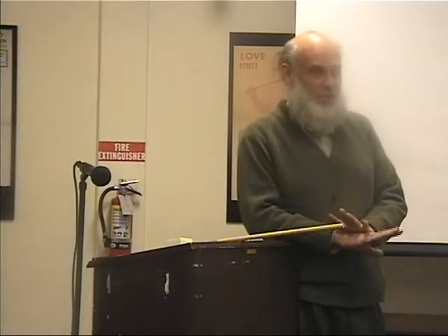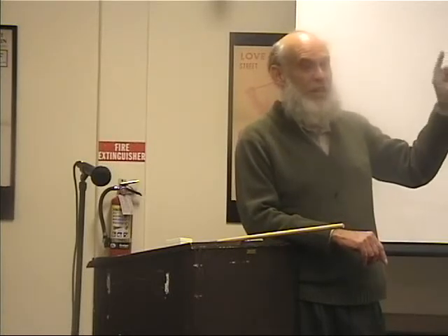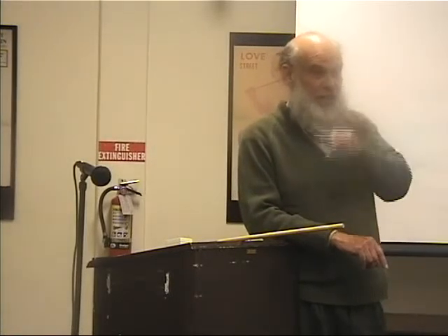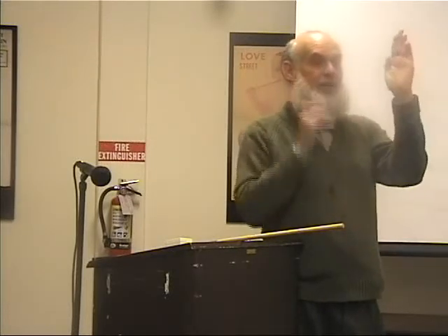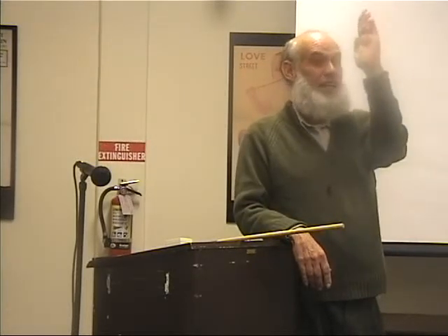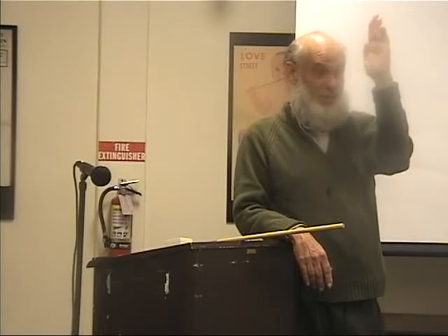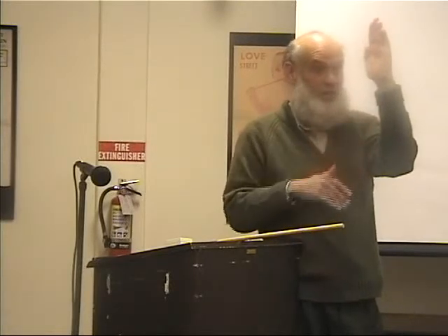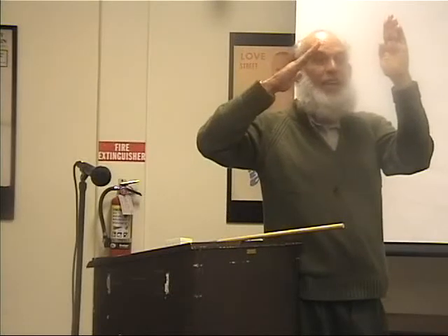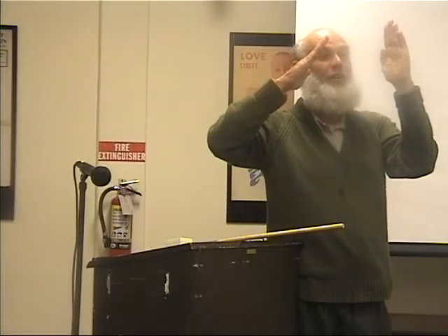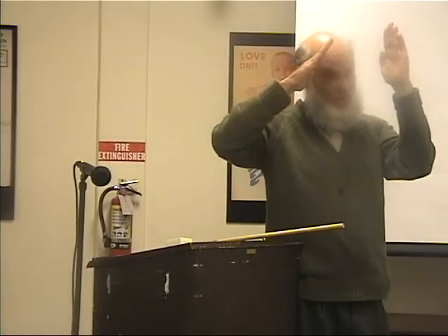If the generators in Las Vegas are attempted to stay synchronous with the generators in Los Angeles, the problem is it takes a certain amount of time for the electromagnetic wave to propagate from Las Vegas to Los Angeles. So if the generator in Las Vegas is sitting at top dead center, so to speak, on one cylinder of an engine, or however you want to represent the phases, the one in Los Angeles has fallen behind by about 1/8 of a cycle.